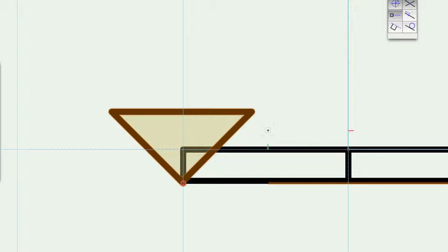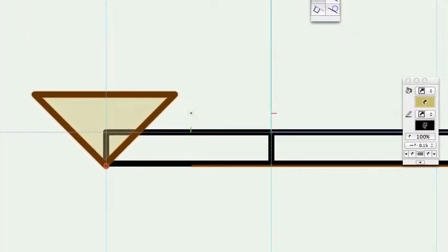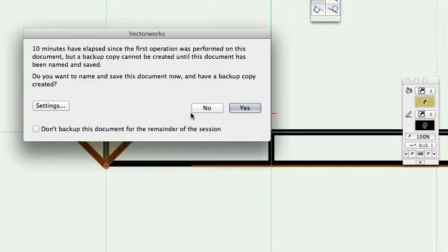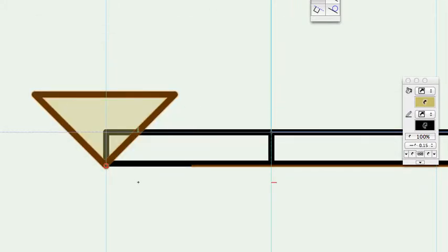Now think about where you are. You're in top plan. You're looking down on this thing. You've drawn a triangle, and the triangle is a flat plane. We need to give it thickness. Well, if we look down, the dimension that we can't see is the 35 1/4, isn't it? Just think about that for a second. We can see the 10. We can see it's 3/4 of an inch in thickness. We can see that the leg is 4 inches, but we can't see the 35 1/4 dimension.